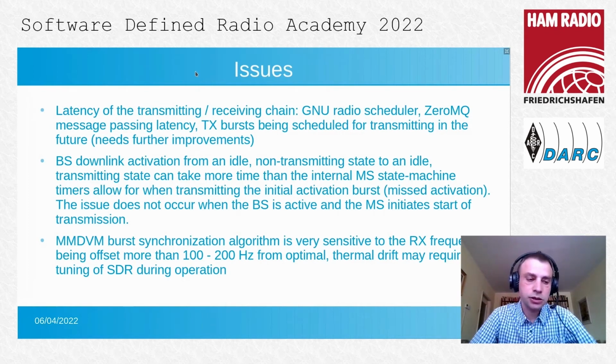Of course, this issue can be mitigated by using a GPS stabilized oscillator for the software-defined radio, which is one of the reasons why the LimeNET-Micro was an attractive target, because it supports using a GPS DO in order to synchronize the local oscillator and prevent it from drifting.